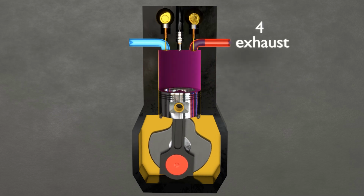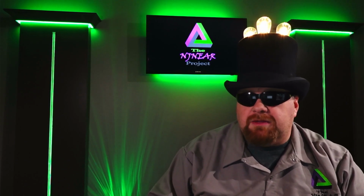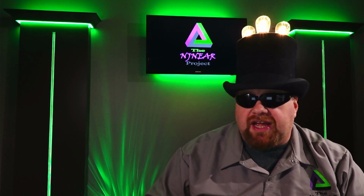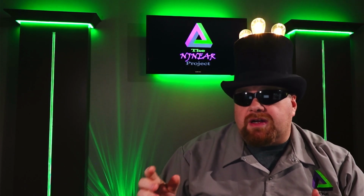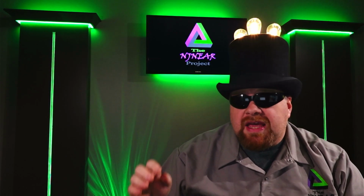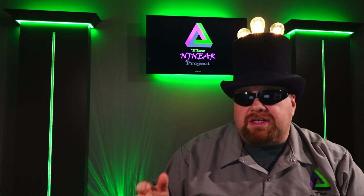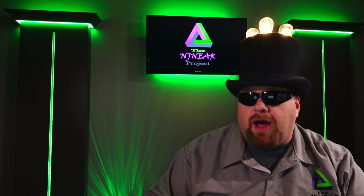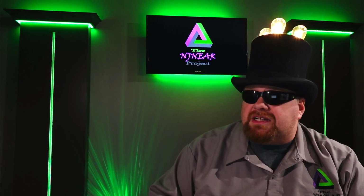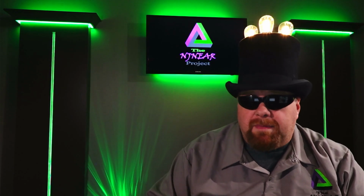When the piston's at the bottom of the cylinder, the exhaust valve opens and the engine begins its final stroke, rising back up and pushing all the spent combustion gases out of the exhaust. And that process repeats itself over and over and over again. So, something to note on top of the quantity of moving components is that only one stroke makes useful energy. The power stroke is not only providing power that the engine makes, it's constantly robbed of power to operate the other 3 strokes. The intake and exhaust strokes are pretty low resistance, but the compression stroke sees quite a bit.